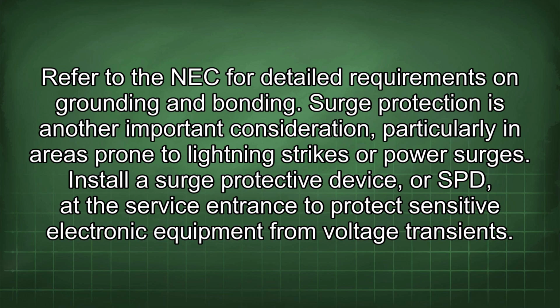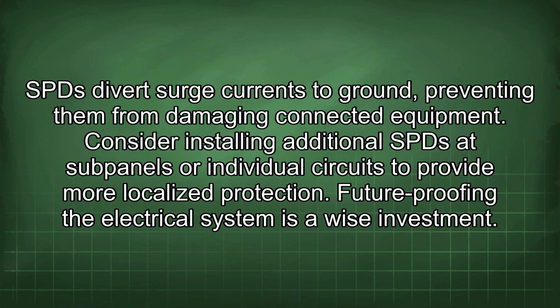Surge protection is another important consideration, particularly in areas prone to lightning strikes or power surges. Install a surge protective device, or SPD, at the service entrance to protect sensitive electronic equipment from voltage transients. An SPD diverts surge currents to ground, preventing them from damaging connected equipment. Consider installing additional SPDs at subpanels or individual circuits to provide more localized protection.